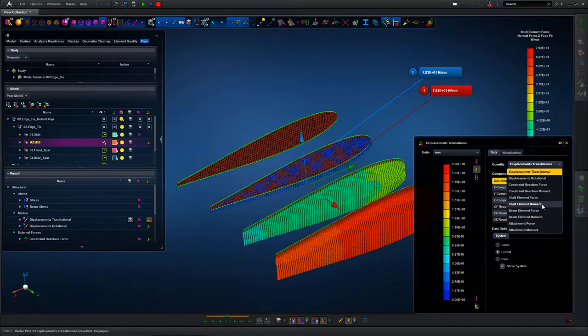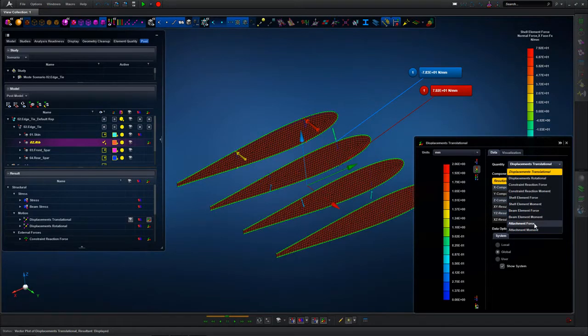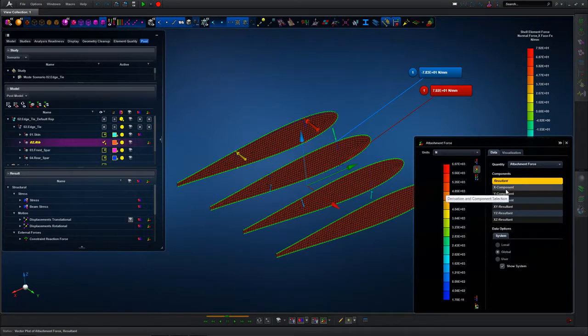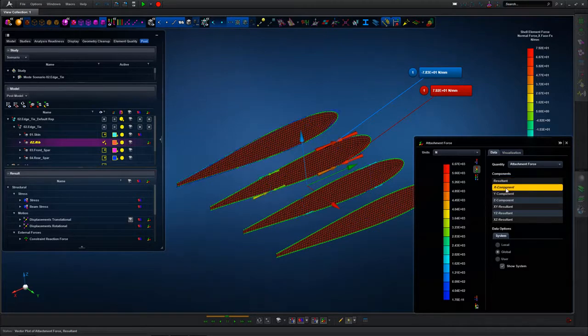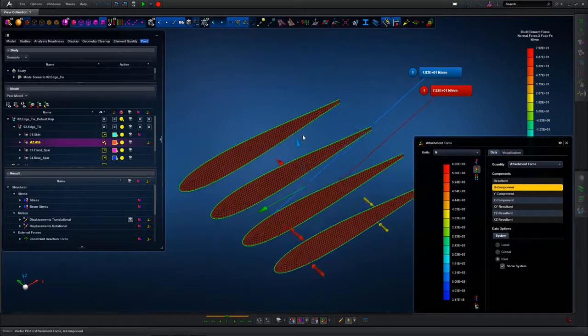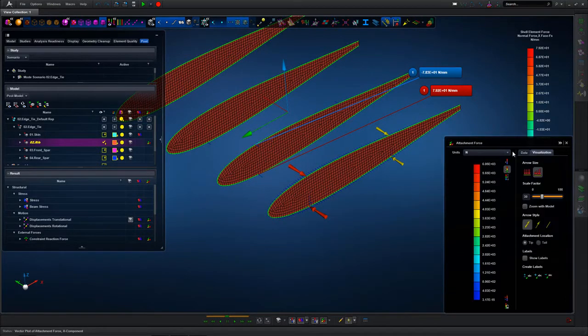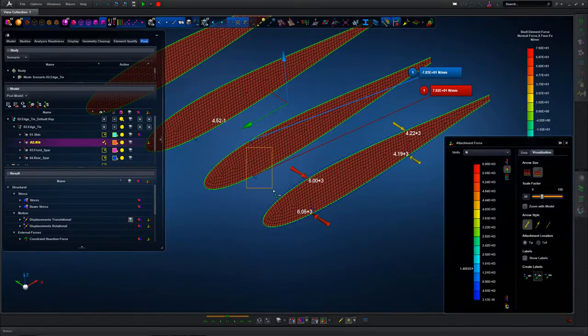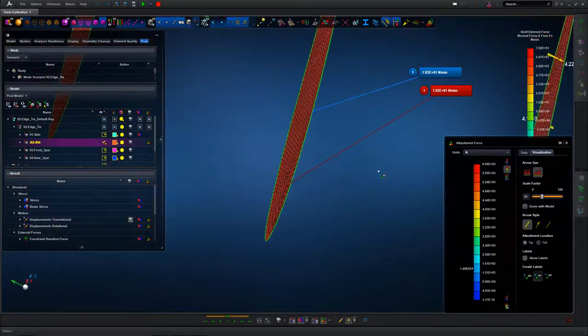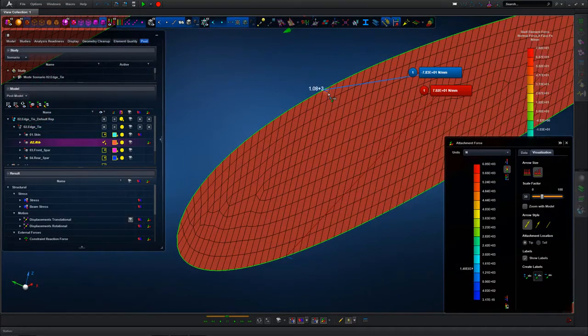So now we're going to look at the attachment forces, which are effectively the loads developed across the edge ties for these given regions. So you could think of these as free body loads acting on the ribs. And if we show a scale plot in that local system again, we can see the interaction between the spars and the ribs due to that wing bending action. So again, we're looking at a local system for the X component, giving us the spanwise action, and that marries up with the standard wing bending response that we would expect.